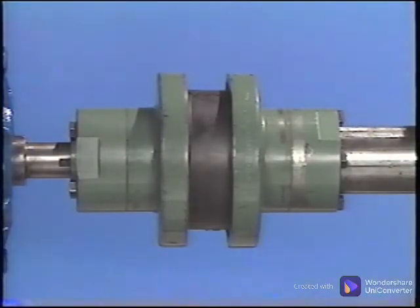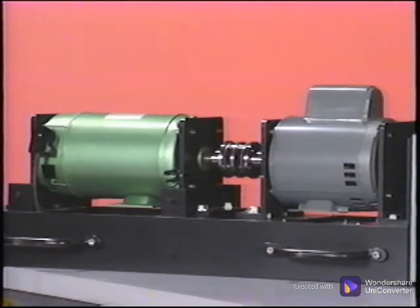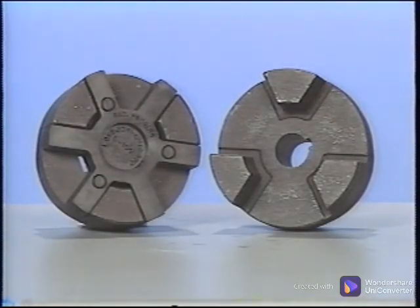In reality, various coupling types produce different responses in spectral and waveform data. In tests performed by CSI, a machine was aligned and misaligned with exact amounts of purely angular or purely offset misalignment and repeated for 5 coupling types. Each setting was run under load and vibration measurements were made. The results varied for the couplings.